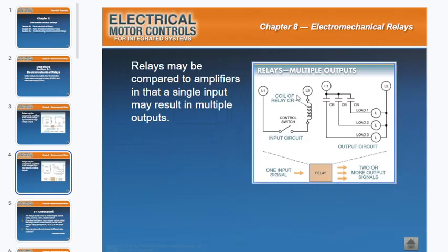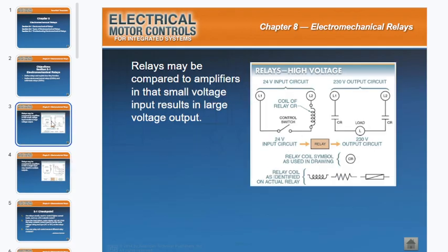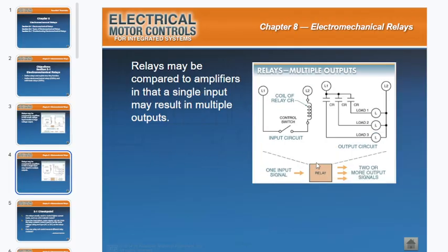all right, if we look at this circuit, it's actually not giving us a voltage, but the first one did give us a voltage, 24 volt input, meaning the coil is rated for 24 volts. With an output, these contacts are energizing a load that's 230 volts. In this case, we're not given the coil voltage, so that's fine because that means this coil could be any voltage. It doesn't really matter. But the point of this one is actually here in this note right above here.